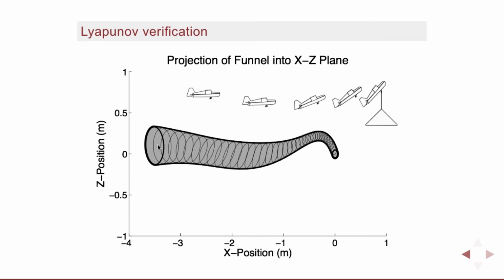It's a good recipe, and really this is the system that made me believe in the trajectory optimization plus feedback along trajectories approach, linear feedback along trajectories. I thought that there was no way that a linear controller along the trajectory would do very well at all on this complicated, highly underactuated system. But in fact, if you watch the system, even with just a simple time-varying LQR controller on it, you'll see, to my eyes, having watched a lot of these planes fly a little bit, very different trajectories where the plane starts with too little energy, and so it actually dips down to gain energy and speed up and get to the perch.